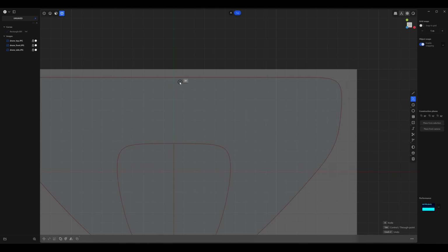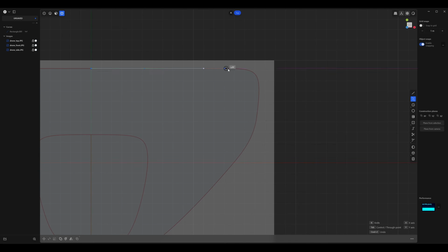Let's start at the top over here. And we're going to try to make this with as few points as possible so that we get a nice curved surface. The first 2 points should be aligned so that you can get continuity. And then we're just going to trace these like so. Every time you go around a curve that has a defined shift or a defined roundness, you probably want to use around 3 to 4 points to define that.